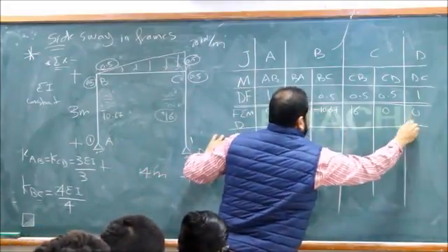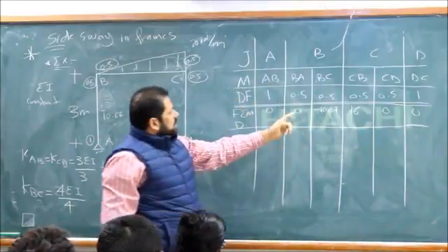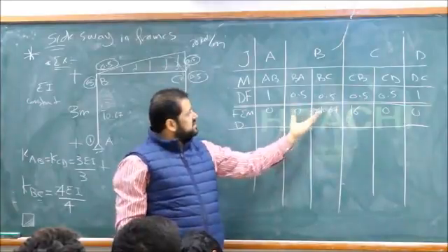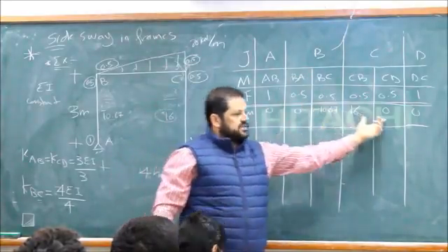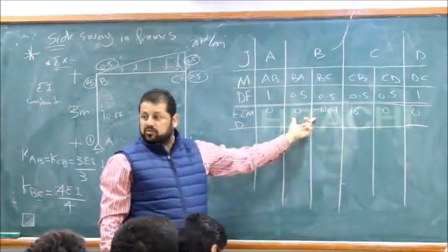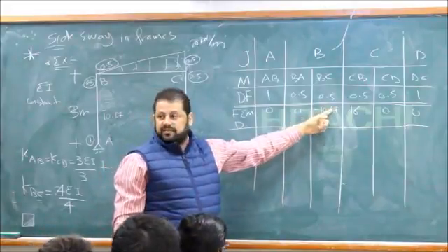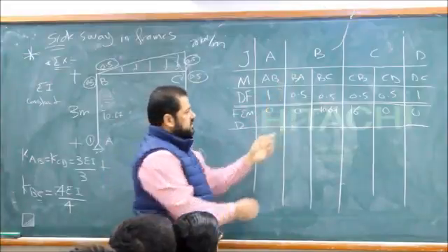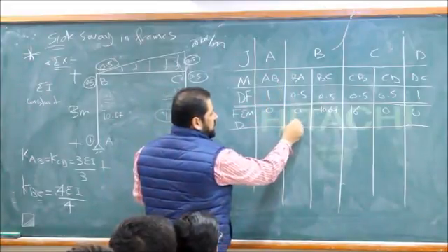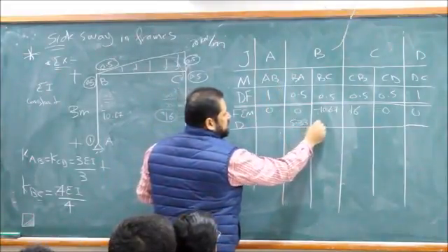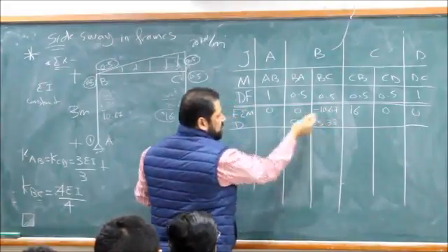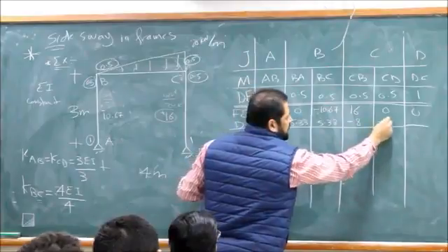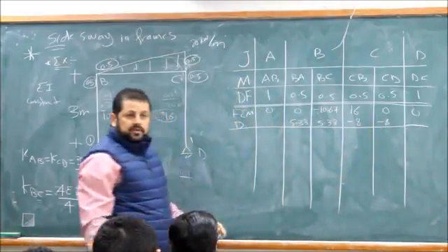Now this joint. No, not this and this. Some of you will add this and this and that. No, this is the joint. This is joint B and this is joint C. Joint B has an unbalanced moment of minus 10.67. We apply 10.67 and distribute. So it will be 5.33, positive. This one will be minus 8, minus 8. Good?